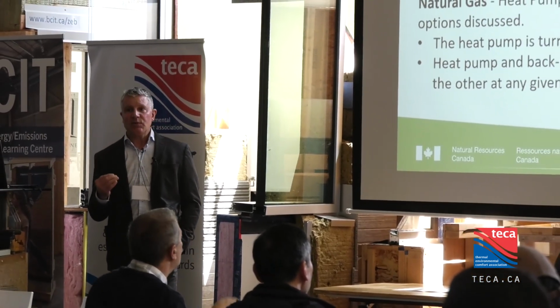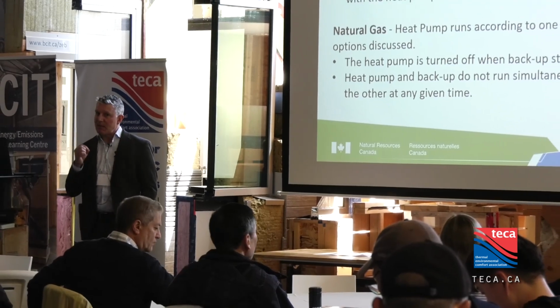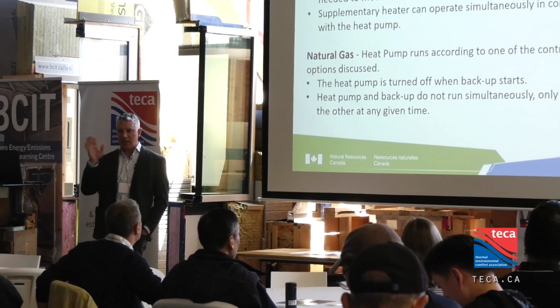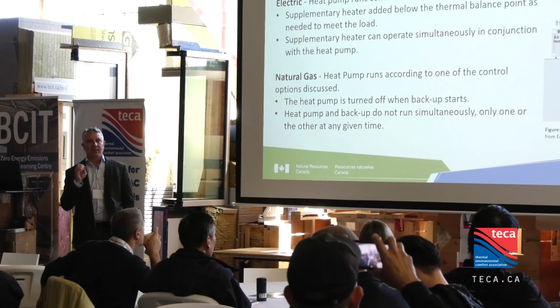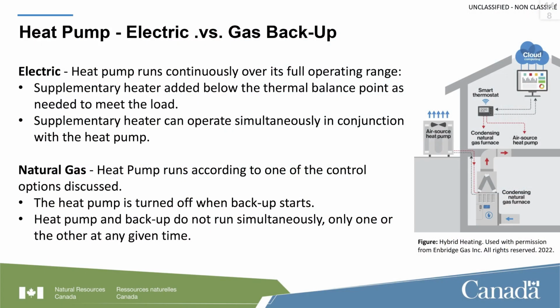But when we have a natural gas backup, right now there might be a few systems out there, some of you might say, I know of one, but typically speaking, the heat pump has to work on its own, and when the gas furnace backup comes on, they cannot work simultaneously for the most part. So the controls there would be different.